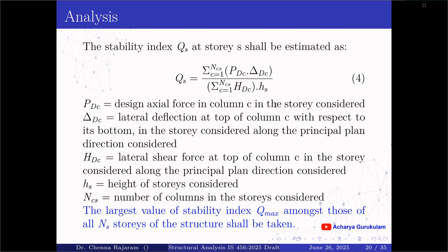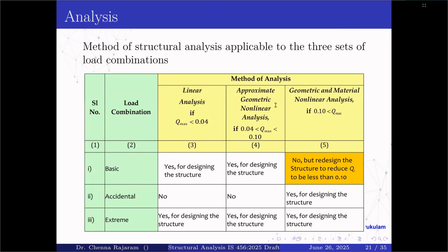The largest value of the stability index, Q max, among the values of all N_S stories of the structure shall be taken into account for the analysis purpose.